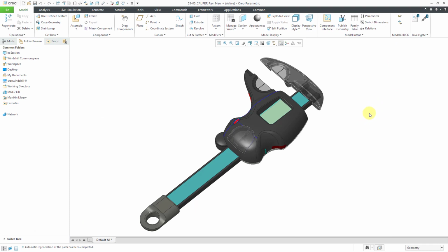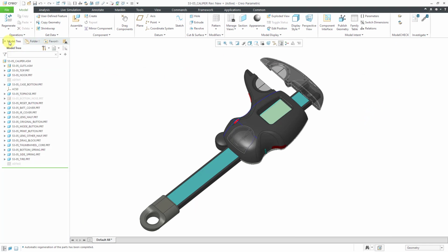So there are a few different methods that you can use when you are trying to take care of these ghosts. The first, probably the best way, is to locate those original files. If you can find them, then put them into Windchill, then this particular model will be able to find its references. But a lot of times that is not possible. A lot of times you will get a model from a vendor or supplier or a partner, and they have no idea where the original source files are for those external references. You might not be able to get to them. So let's take a look at how you can solve the problems and break those references to the ghost objects.